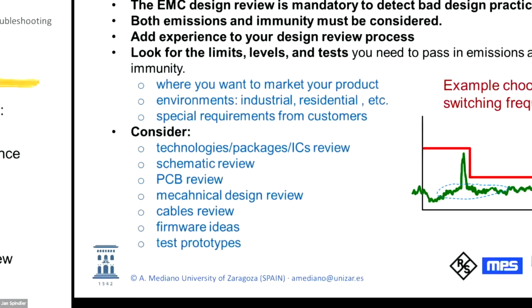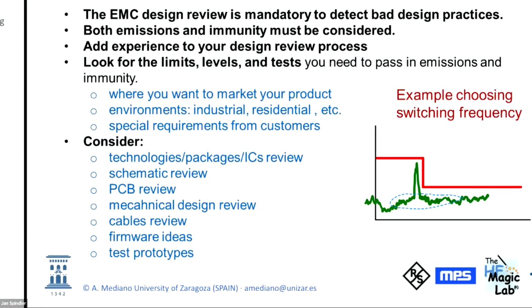Another important idea is to consider different elements. People usually, when doing EMC review, check, of course, the schematic, sometimes the components, and of course, the PCB. But it is not usual to review the mechanical design or the cables, especially the mechanical design.